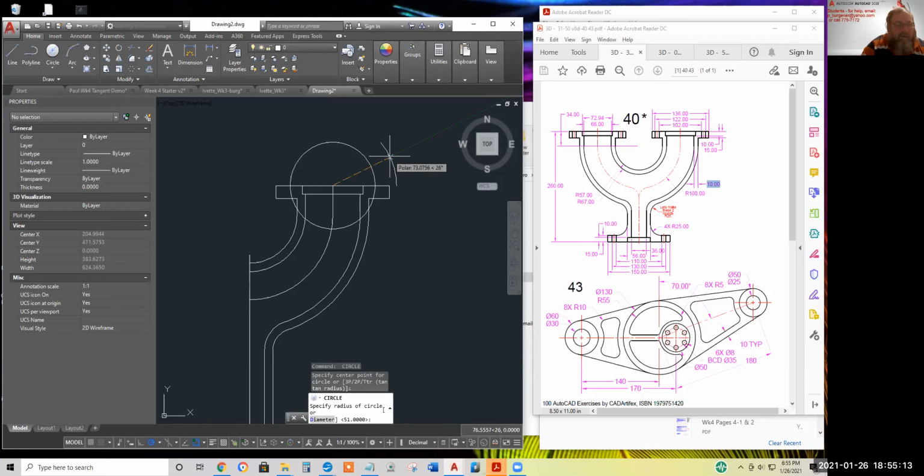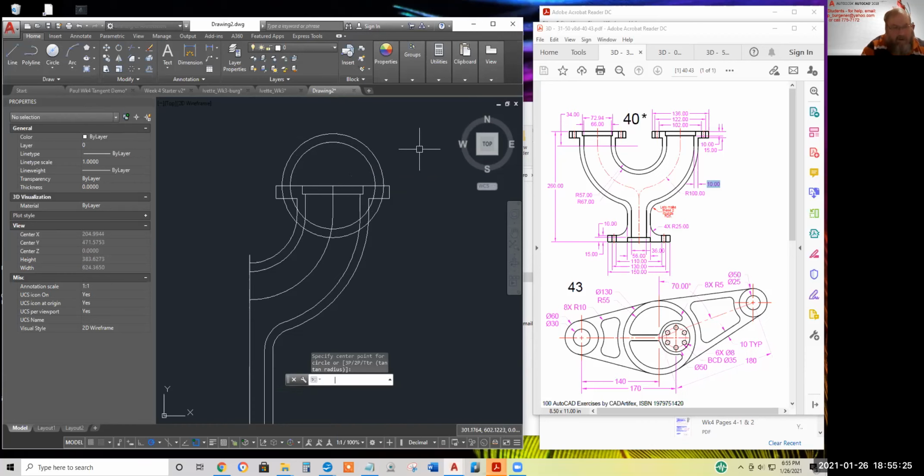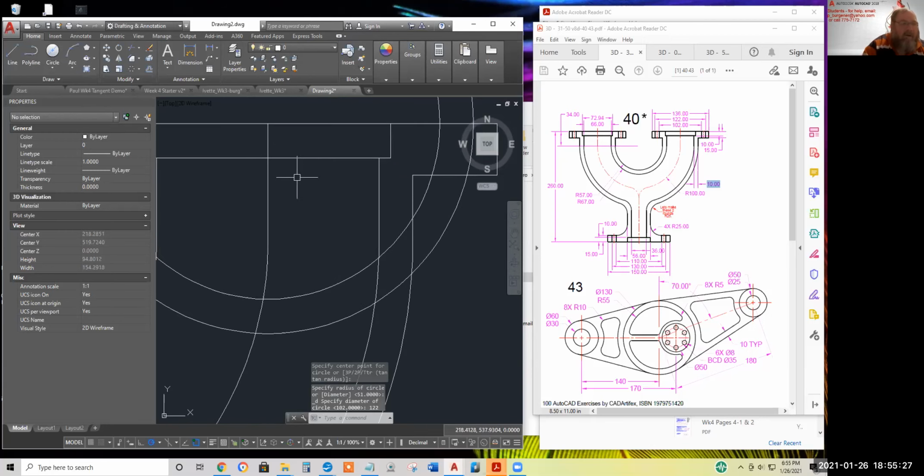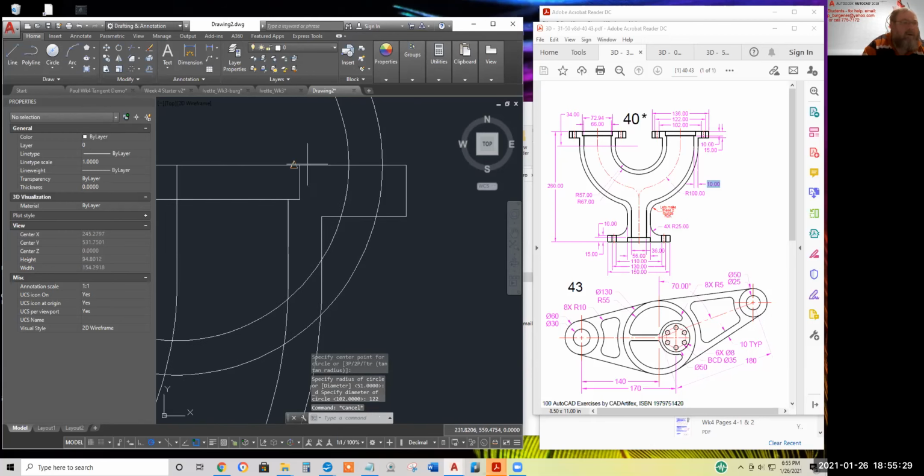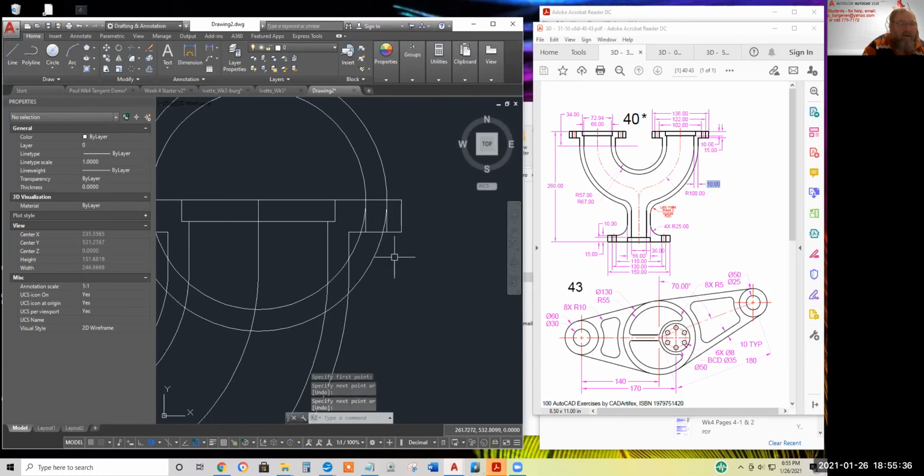And yep, see, I hit enter to invoke the last used command, but need to go to the icon again. And the outer surface of those holes is 122, enter. Zoom in, O snap, intersection straight down, enter, straight down. I can lose these two and mirror that across.